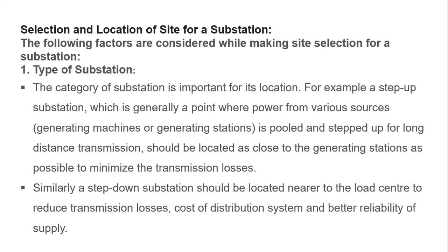Okay, understand, first which substation we want to install, we have to select which type of substation. Which type of substation is to be installed? Okay, for example, we are installing the step-up substation. Step-up substation means that we are using the step-up transformers. Therefore, this will be located near to the generating stations. Why? Because it is near to the generating stations, we are minimizing the transmission losses.